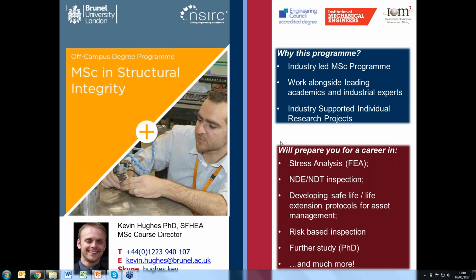NDT is an important aspect, in addition to working in careers where you're looking into asset management. So this could be for life extension, to see whether a structure that was made, say, 20, 30 years ago, is still compliant against current codes. And as part of that, looking into risk-based management inspection strategies as well, and how to remediate any risks that can occur.